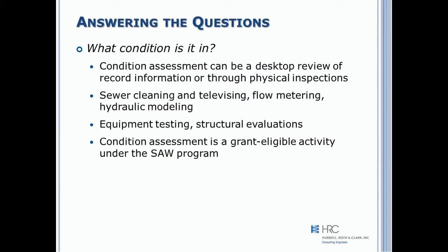So the next question, what condition is it in? Condition assessment can be estimated using a simple desktop review of basic asset data such as age and repair history, or you can do a more accurate and detailed collection of information through physical inspections.